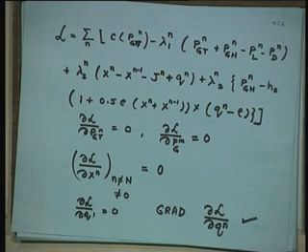Calculate the gradient, again see whether you satisfy the optimality conditions or not. That is the 3 conditions: gradient 0, gradient positive or 0 for the lower limit, gradient negative or 0 for the upper limit. And then the problem is solved. You can instruct your operator, look, operate at this value, operate at that value, and you get the optimal hydrothermal solution.